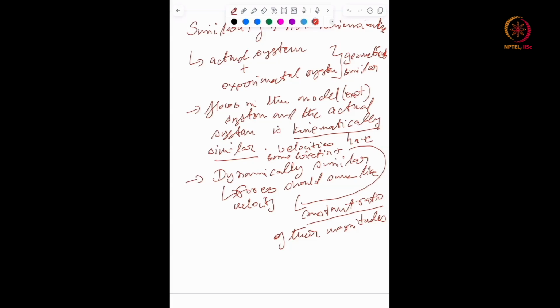So when two systems are similar, the results collected in one may be used in the prediction for the other, following proper scaling, that is, resizing. That means measured flow properties are normally dimensional, because what we measure is an actual velocity with a number. Non-dimensionalization is the process of converting these measured properties into non-dimensional numbers by utilizing their appropriate scales.